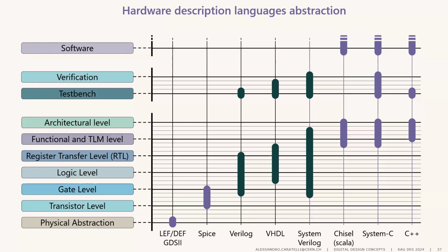Let's say you mostly work at the functional or RTL level. There are some cases where you really want to optimize some circuit, so you want to describe it at, let's say, logic level, just placing actually the standard cells to do some very optimized circuitry. It's a bit more rare. So, for instance, on the project I'm working on, I'm doing this only inside the pixel. I really want to optimize the area, and I'm using some asynchronous state machines, so some particular things. So then I'm writing at a lower level. Otherwise, you generally don't.